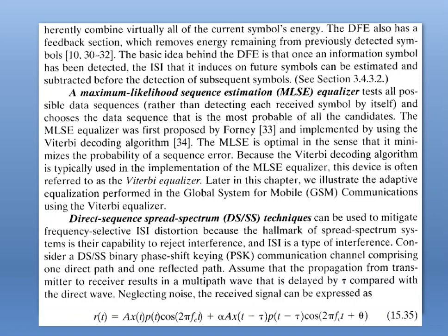The MLSE equalizer was first proposed by Forney and implemented using the Viterbi decoding algorithm. The MLSE is optimal in the sense that it minimizes the probability of sequence error. Because the Viterbi decoding algorithm is typically used in the implementation of the MLSE equalizer, the device is often referred to as a Viterbi equalizer.